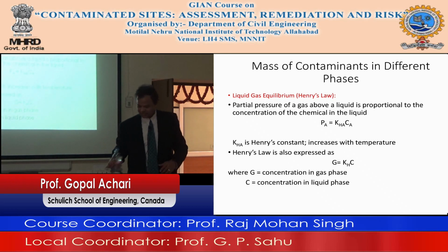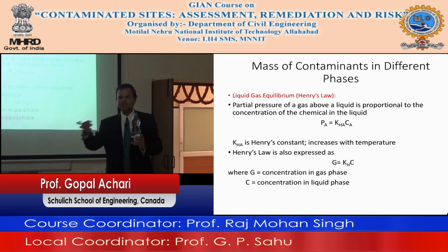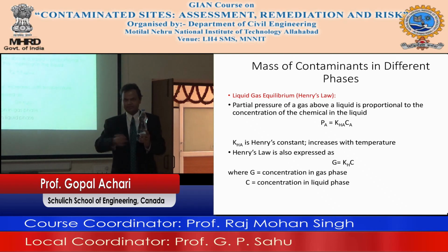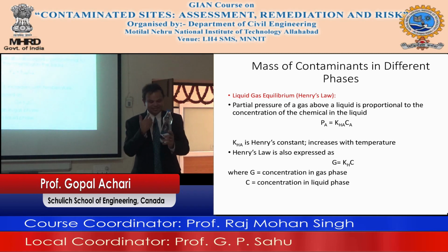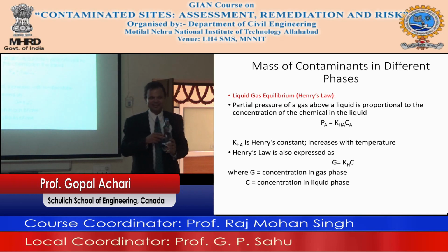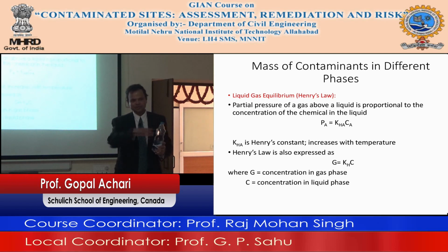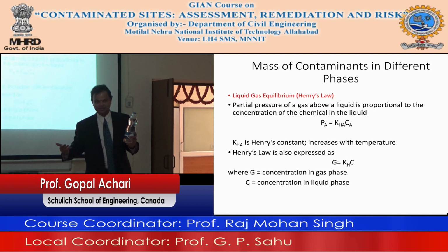What did I do here? I took the cap, I removed the air, replaced it with fresh air. If that is my mechanism to remediate this water, I will replace the air and I'll continue to replace the air. So I replace this little amount of air. And if I'm a novice, if I don't know what I'm doing, I replace this air and I say, the benzene is gone, right? But 2 hours later, it's still moving from here to here. And I say, okay, let's do it again. Okay, mistake made, a little bit got done. I'll remove it and do it. I remove the water again, the air again. Again, I find the same thing.